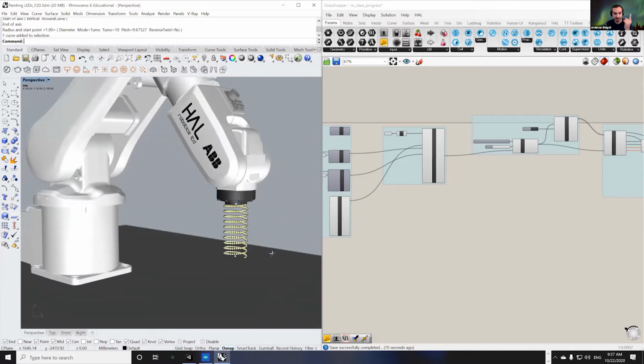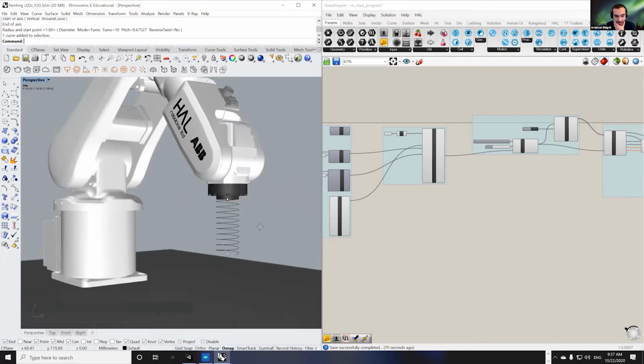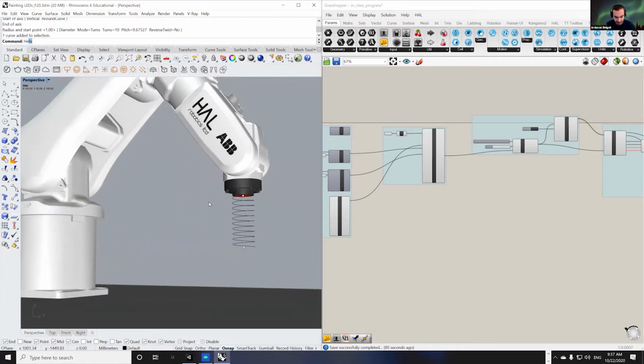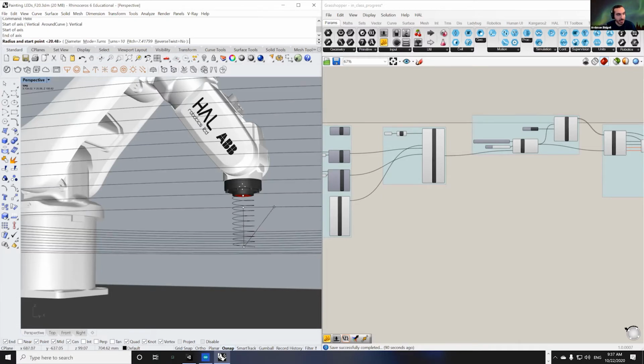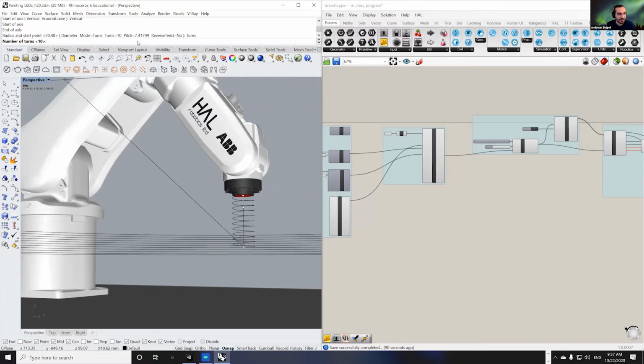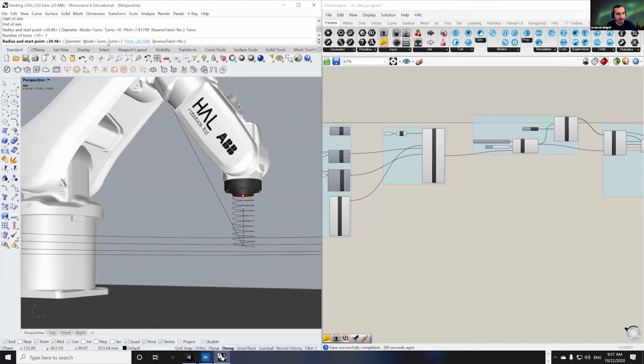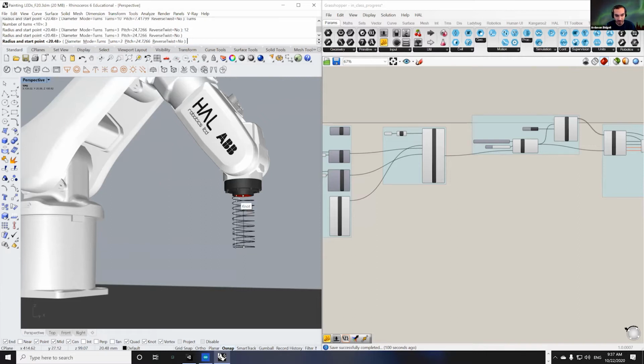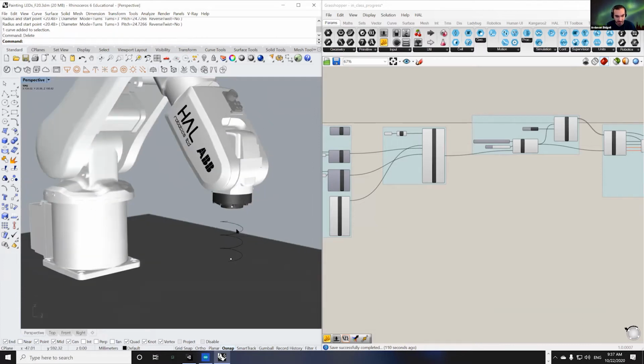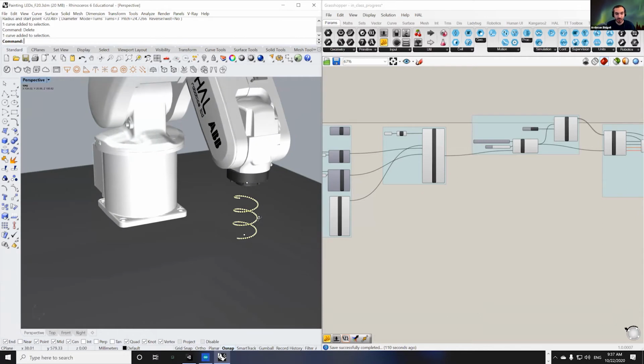It's a helix, it's a spiral that moves up. So you should have something like this. So the command is called helix. And you can actually by default select a vertical one, select 1 point, then select another point. And you can say that maybe it can have 3 turns, and you can set the diameter for something like 12. Maybe that's a better one. And you get one. Oh, let's see. Okay, good. The other one was too complex. Okay, so we have a helix here, or any other curve that goes up is fine for this workflow.